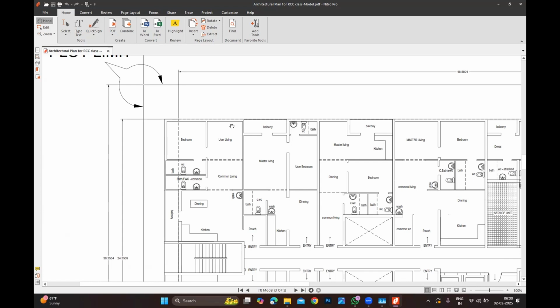See, 8.5, I'm saying, when the architectural people are starting from scratch with the concept design, if you could have been involved during that time and given them the information, saying place the columns at 8.5 meters, they will arrange the room dimensions accordingly. Even 8.6, 8.4, 8.3 doesn't matter.